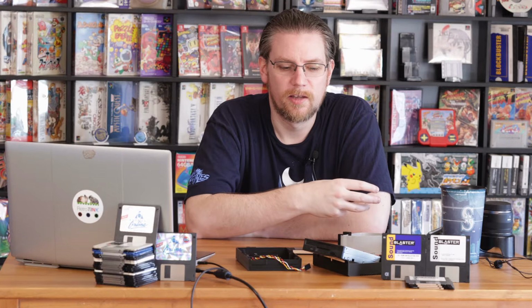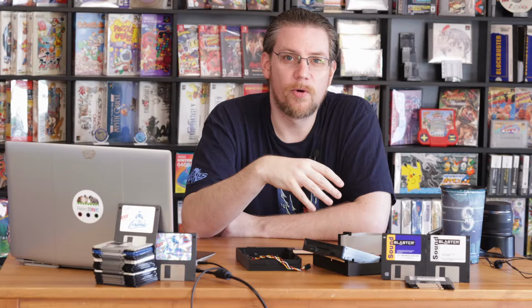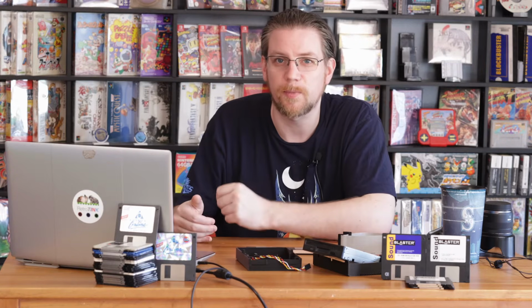In a recent video that I published, I showcased the oscilloscope that I just got, showcasing that digital computers still live in an analog world. So what we think of as a 1 or 0, there's actually a whole array of voltages in between, and depending on where that voltage sits, for instance, a 5-volt signal needs to be above 4 volts to register as a 1 or below 2 volts to register as a 0, just as an example, and anything in between is kind of floating.